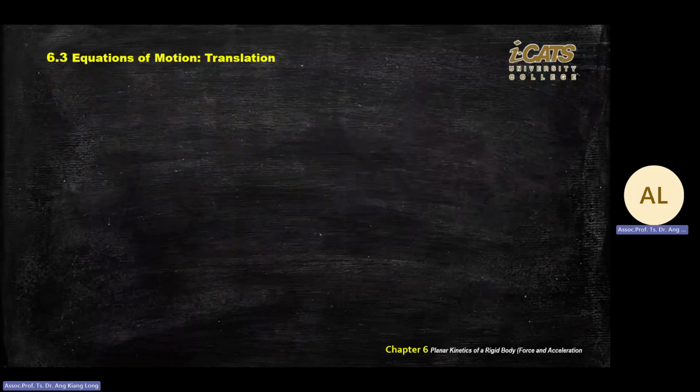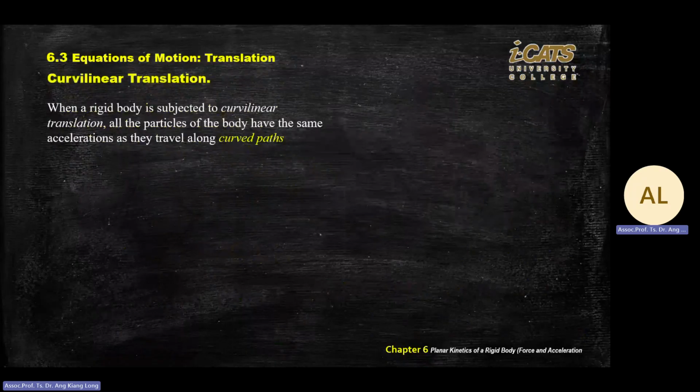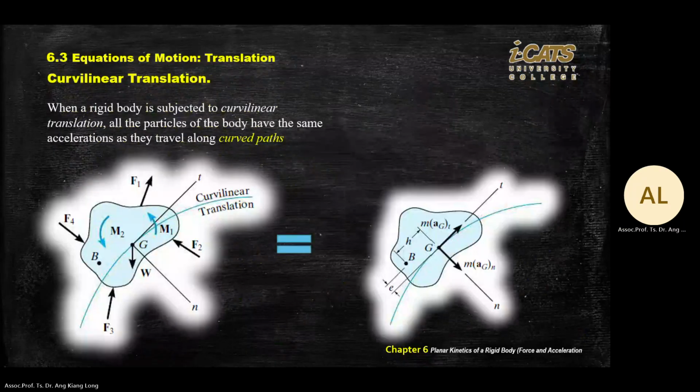Curvilinear, just remember, every time you see curvilinear motion, you break all the forces into tangent and normal directions. That is the revision of what you have learned. Although it looks very complex, what I need to remind is to break all the forces into tangent and normal directions. Normal always points into the curve. Tangent always follows the velocity of the object. So this one, you know that if you're pointing this way, it means the question already gives you anti-clockwise rotation.